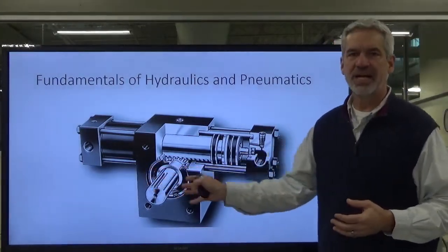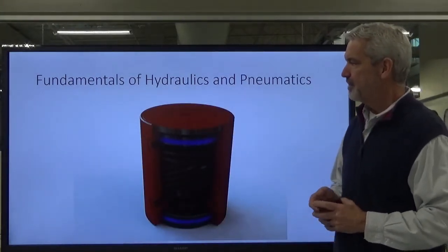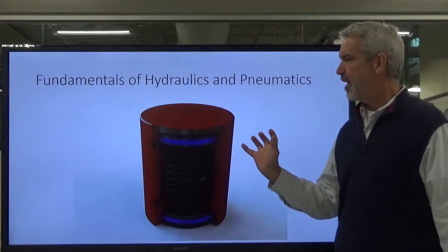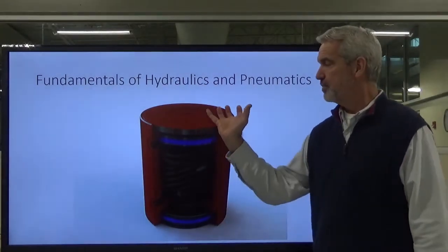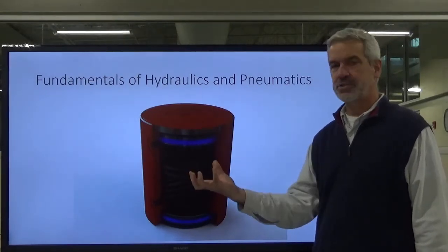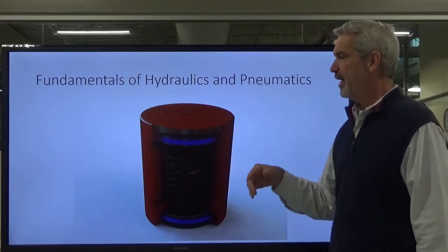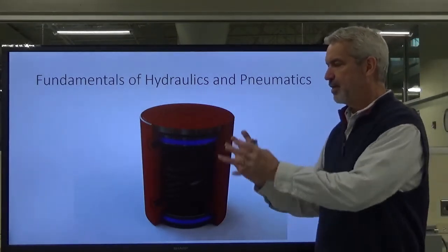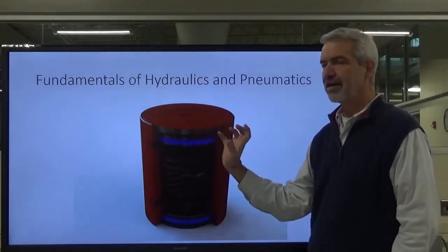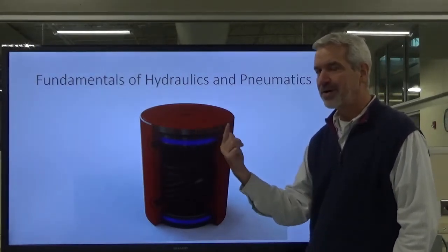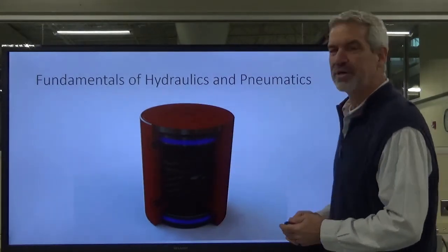But this is a rotary actuator. Another type of rotary actuator as well. I've worked with these before, where tractor trailer wheels sit on there, and they would have to be indexed a certain number of degrees and get welded. So the wheel would get on the actuator and turn X number of degrees, and this actuator is just going back and forth. It's not going around and around. It's just within that 360 degree range, going back and forth. So that's a rotary actuator.